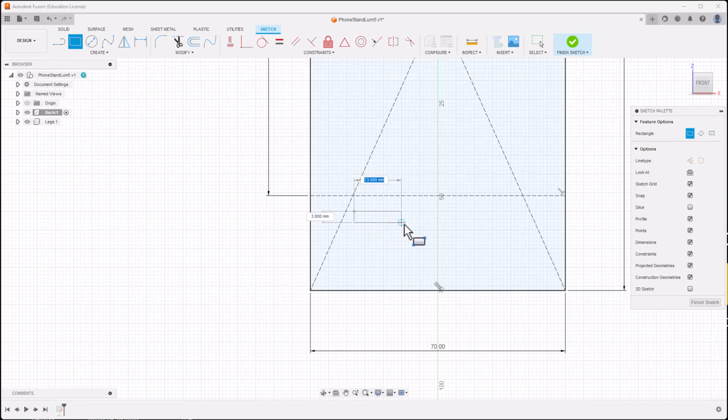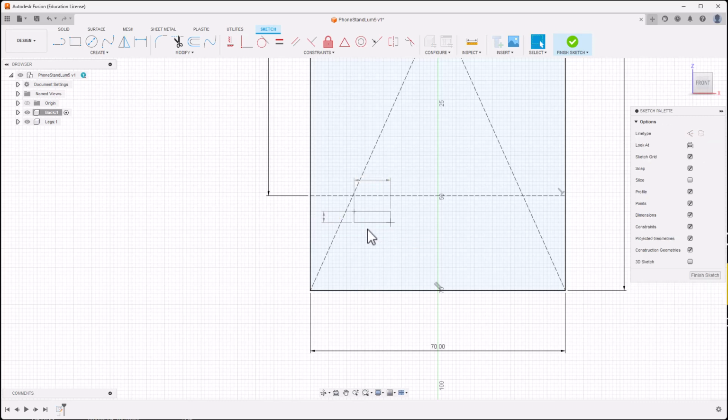I'm going to create these 3 rectangles. I'm going to do the length first. I hit tab to do that. That's going to be 10. And then the height of these things, this is one of those dimensions that matters how thick your material is. So I'm going to hit T for typing in a number, but I can actually type in letters. And notice once I bring up T, it brings up this user parameter thickness. Put that in and hit enter.